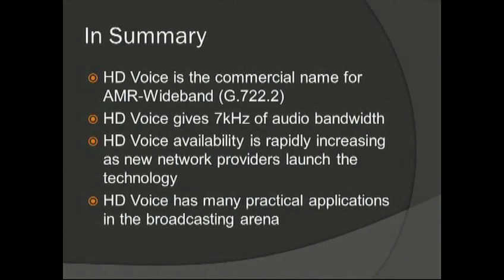So in summary, HD Voice is a commercial name for AMR wideband codec. It gives you 7 kilohertz of audio bandwidth. The number of service providers is rapidly increasing, and it has many practical applications for you as broadcasters.